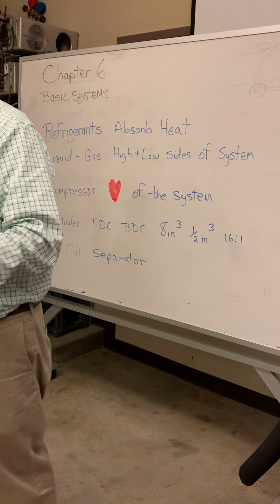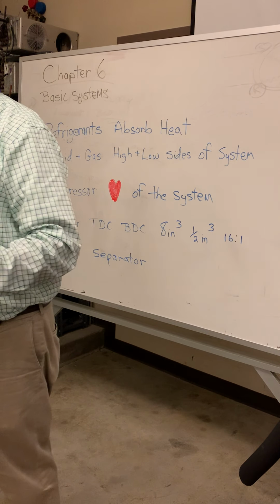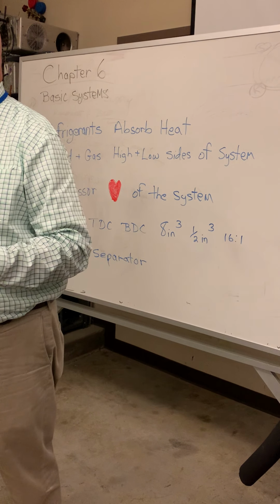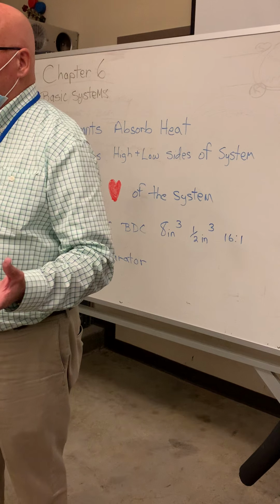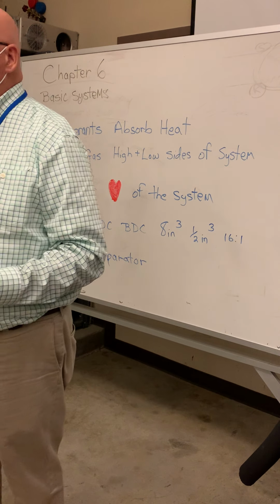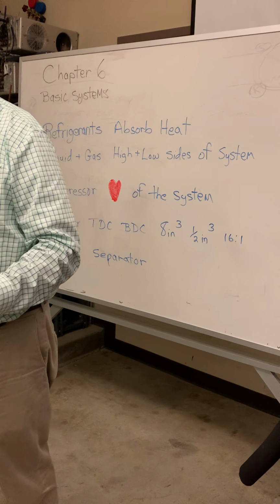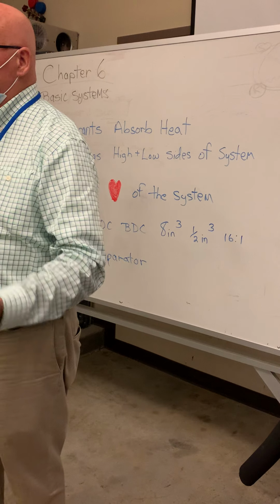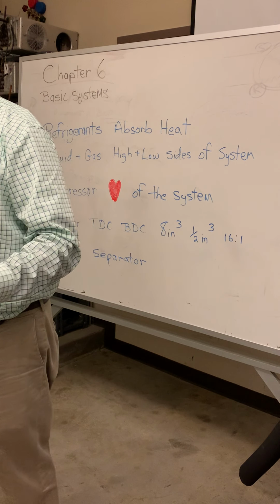So when you go out and start doing HVAC work, the first thing you're going to do is buy 2 sets of gauges. You're going to buy one set of gauges that can be used with the synthetic oil, and then you want another set that's used with the natural oils. And it depends on the refrigerant.